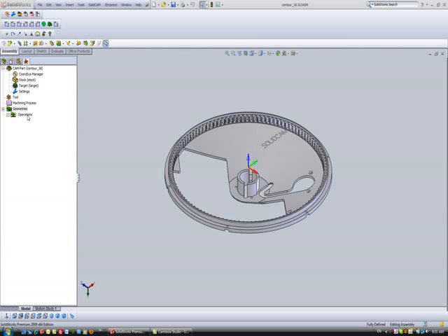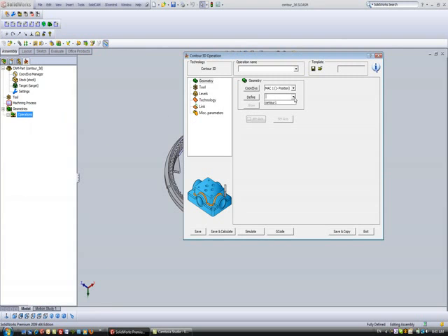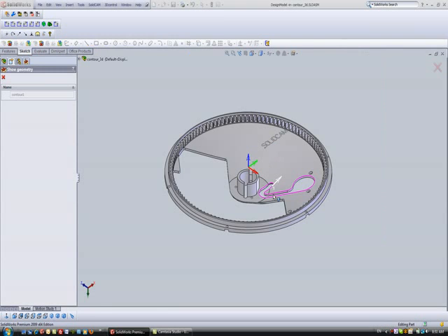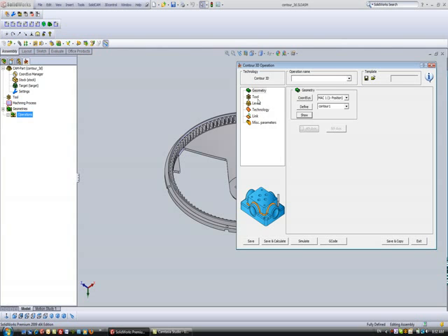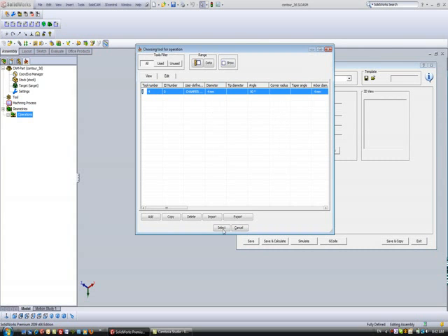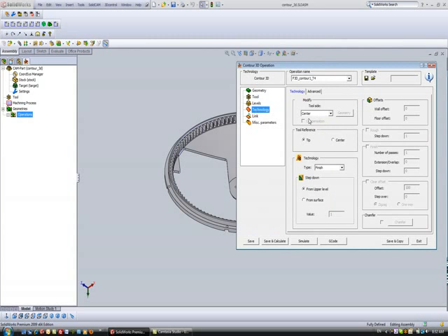In this last part, I'd like to show some of the improvements we've made in Contour 3D. I'll start my operation of Contour 3D. My geometry in this particular case will be this area over here, this curve over here. And what I'd like to do there is actually put a chamfer on that edge. So I'll use a chamfer tool of 4 millimeters. And in my technology area, you'll note that we have here center. Center will actually allow it to go directly, the center being on that particular geometry. But in this particular case, I'd like to go on the left hand side of the geometry.